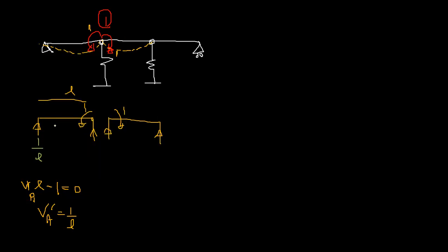So considering the vertical force equilibrium, we don't have any vertical loading because this is the redundant applying occasion. In the primary structure, we had the loading. Here we do not have anything. We apply just the unit forces at the coordinates we have, right? So 1 over L. So this should be then minus 1 over L.